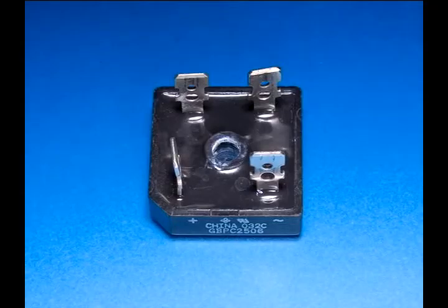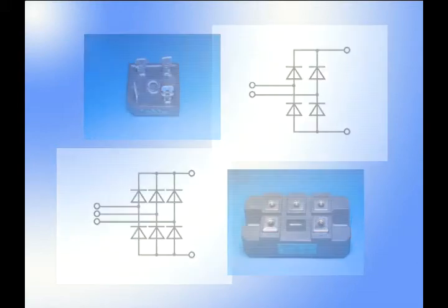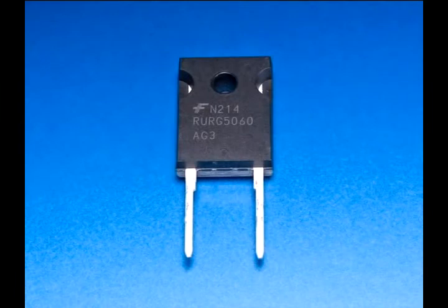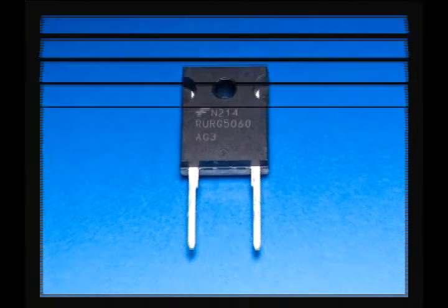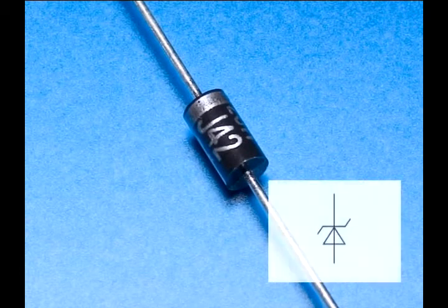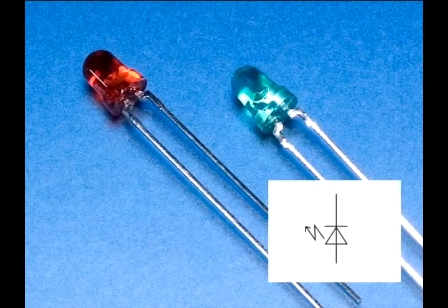There are various types of diode. Let's look at some typical diodes. This one converts single-phase AC voltage, or three-phase AC voltage, into DC current. It is comprised of 4 or 6 diodes and has a synthetic resin cover. This is another type of diode. It is used when a high-speed operation such as DC power supply or inverter functionality is needed. Among other types of diode are the Zener diode and LED. Its advantages are low power consumption and long life.